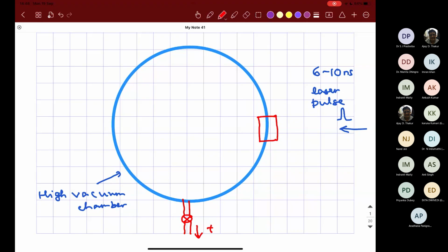So typically in a schematic, we show a vacuum pump. What kind of vacuum pump we will see today in the lab. Primarily, one of the possible choices is a turbomolecular pump backed by, say, a rotary pump or a scroll pump. That really allows you to achieve very high vacuum. Why high vacuum? Because initially you need to clean the inside of the system of any impurities. So when we have this vacuum pump, we can evacuate to very high vacuums.